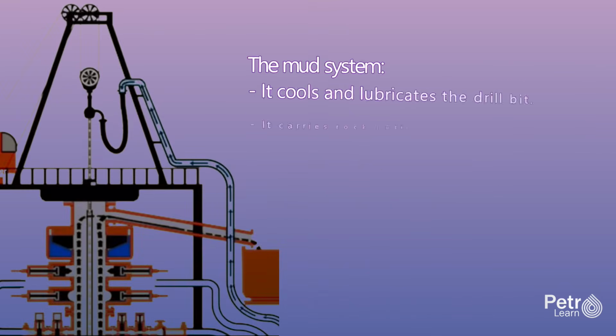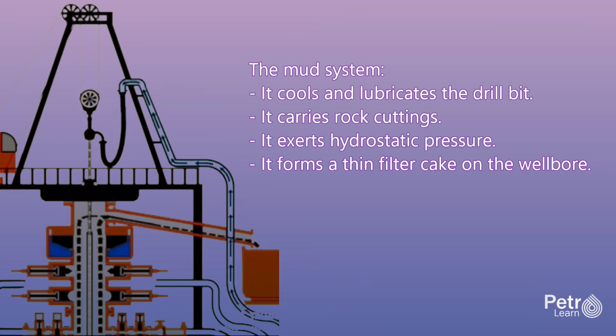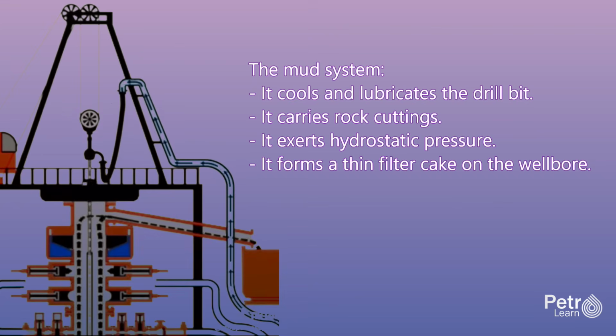Drilling mud is a specially engineered drilling fluid that performs multiple critical functions. It cools and lubricates the drill bit, which can reach temperatures over 400 degrees Fahrenheit from friction and bottom hole temperature. It carries rock cuttings up from the bottom of the hole to the surface. It exerts hydrostatic pressure on the formation to prevent formation fluids from flowing into the wellbore. It forms a thin filter cake on the wellbore wall that prevents fluid loss and stabilizes the hole.